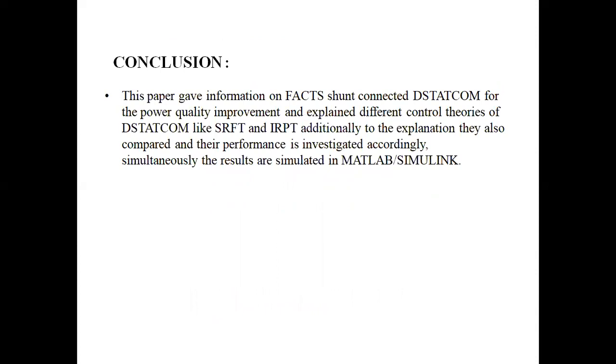The conclusion of our paper is that this paper gave information on the shunt connected DSTATCOM for power quality improvement, and explained different control algorithms of DSTATCOM like SRFT, synchronous reference frame theory, and IRPT, that is instantaneous reactive power theory. In addition to the explanation, they were also compared and their performance was investigated accordingly. Simultaneously, the results are simulated in MATLAB Simulink.